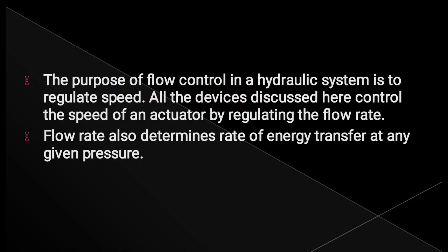The purpose of the flow control valve in a hydraulic system is to regulate the speed. So why do we have to control the flow? As we know, in many industries we have a lot of operations, for example to and fro operations. Some of those operations have slower speeds and some have higher speeds. With respect to the application, those slow and high speeds can be controlled only by flow control if it is a hydraulic system. So we have to use flow control valves that control the speed of that motion.